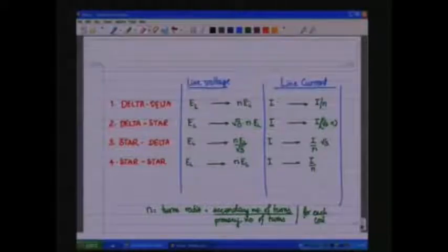So, in the case of the delta for the same power and voltage ratings, this is supposed to have a higher core cross section area to withstand a higher voltage, but the gauge of the wire will be thinner, and in the case of the star it can withstand a lesser voltage, but the gauge of the wires will be thicker. Anyway, depending upon the application, the relationship between the voltage and the currents, one of the 4 types of configurations or topologies can be chosen.